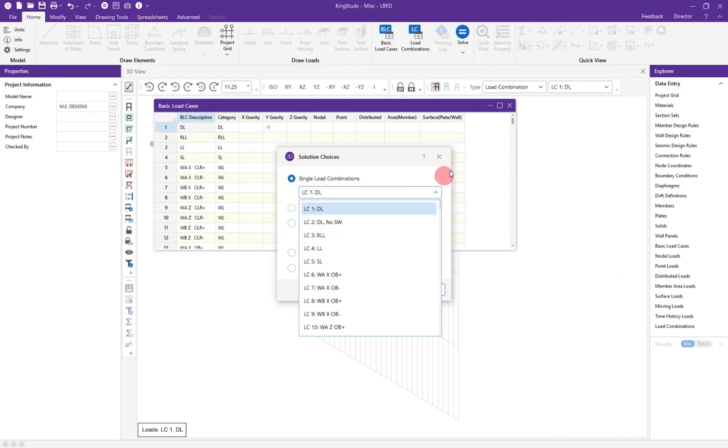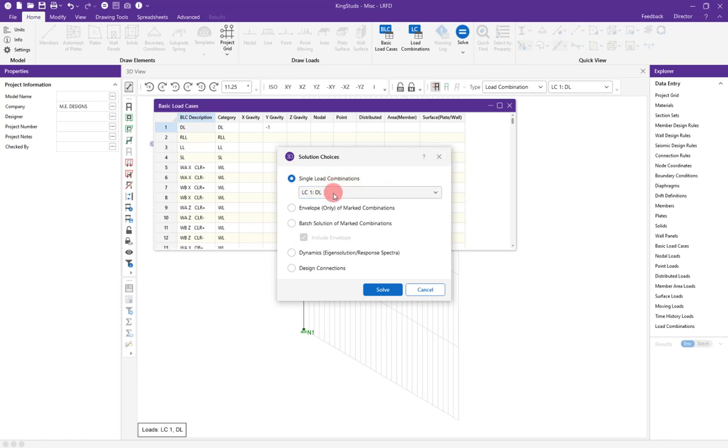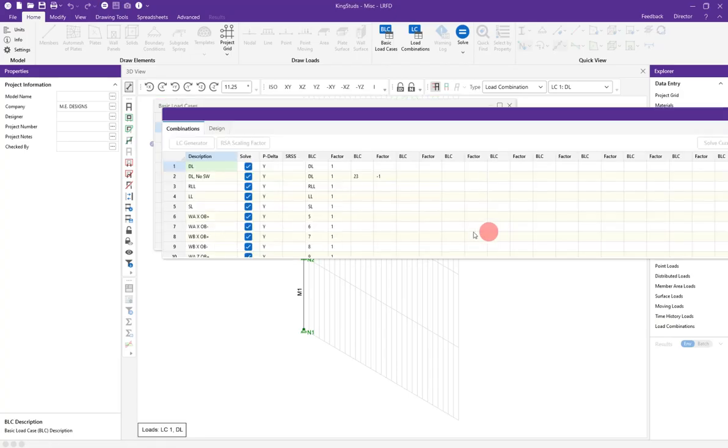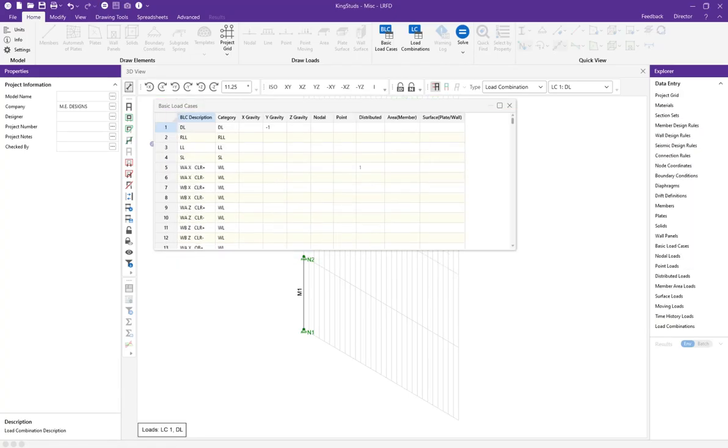That's the reason. Okay, so this is pulling load combinations right now. If I go look at the load combinations, these are the combinations which are referring to these load cases. So these are all the load cases, like when there's not a label, like this is a label for wind load, but when I need to differentiate what it is, I have to use a number as opposed to dead load as this. So this is made by category. These ones down here are referring to the number of the load case. Does that make sense?